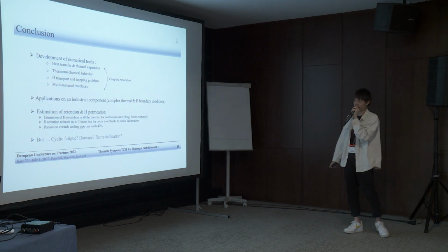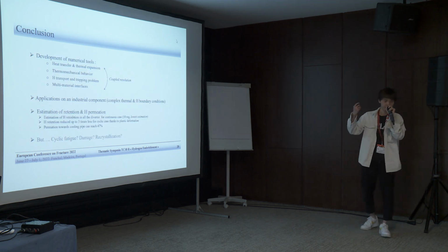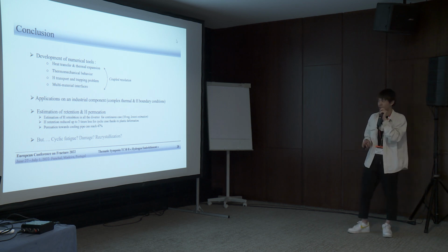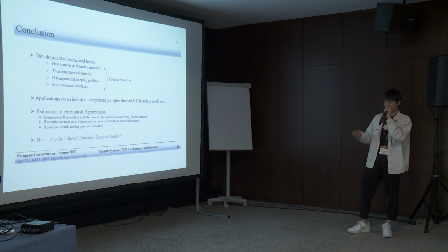The conclusion is that we succeeded in making a numerical implementation with some Abaqus user subroutines to solve such a highly coupled problem, and in realizing some applications on industrial components, we are able to make an estimation of hydrogen retention and the hydrogen permeation inside the material.